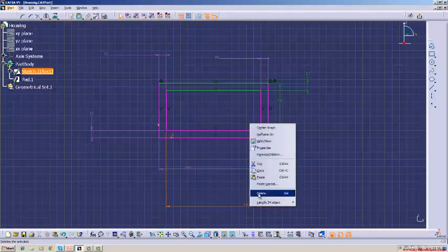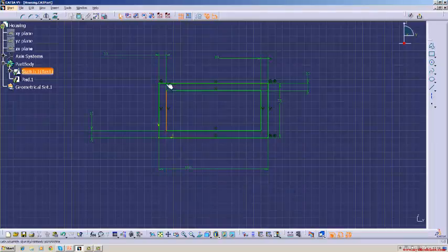I will tell you what constraint means. This is 130. Now this is 10. This is 10. Total is 150. So 150 minus 20 is 130. It is already there, 130. If you change any one of these things, automatically the line is adjusted. So if you assign a value here, it cannot maintain the value. It will change depending upon what value you give to the 10 and 10. So you need to remove one of the constraints. That's why we cannot apply that constraint.